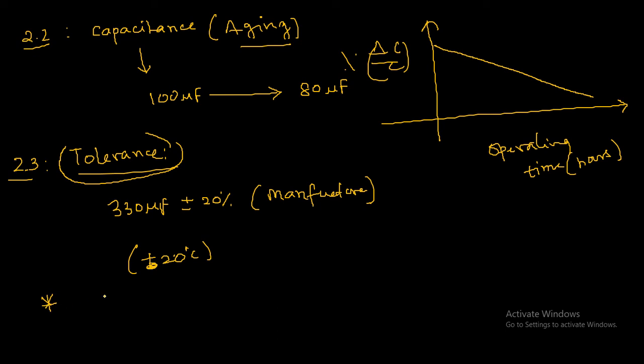It should be pointed out that the capacitance tolerance is only ever defined as a possible deviation from the capacitance at the time of delivery and does not apply for the entire period of use or product life of the capacitor, because there are other factors that also influence capacitance changes. Just like we have discussed, one of the parameters, aging.